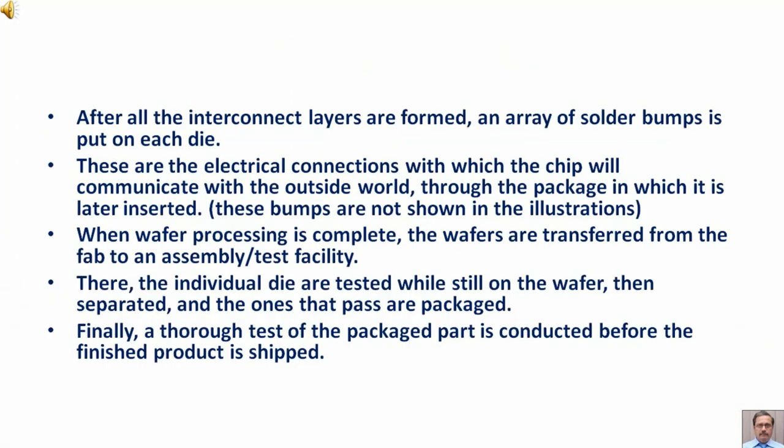After all the interconnect layers are formed, an array of solder bumps is put on each die. These are the electrical connections with which the chip will communicate with the outside world through the package in which it is later inserted. These bumps are not shown in the illustrations.